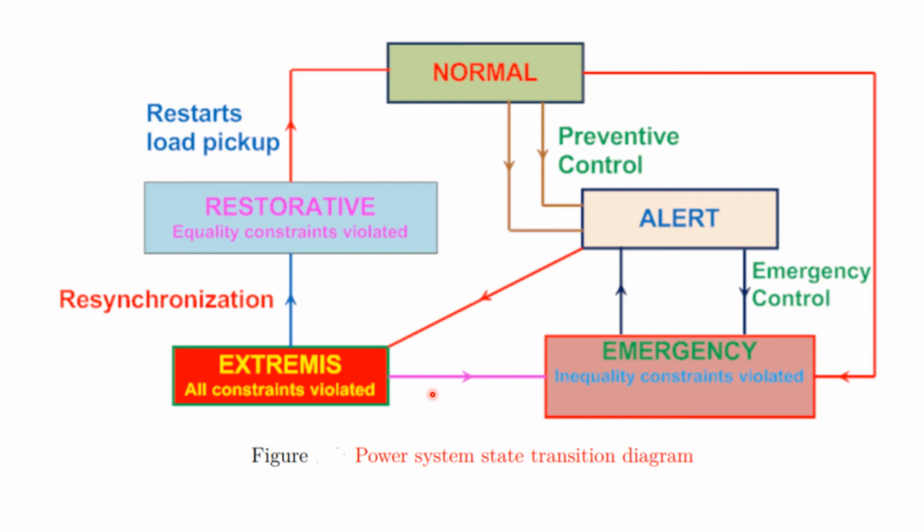We bring back the system from the islanding condition to emergency or normal state. That means the generation will be satisfying the demand. If the components are overloaded, the active power balance is disturbed, so you should strip the proper generation, that means load shedding properly.